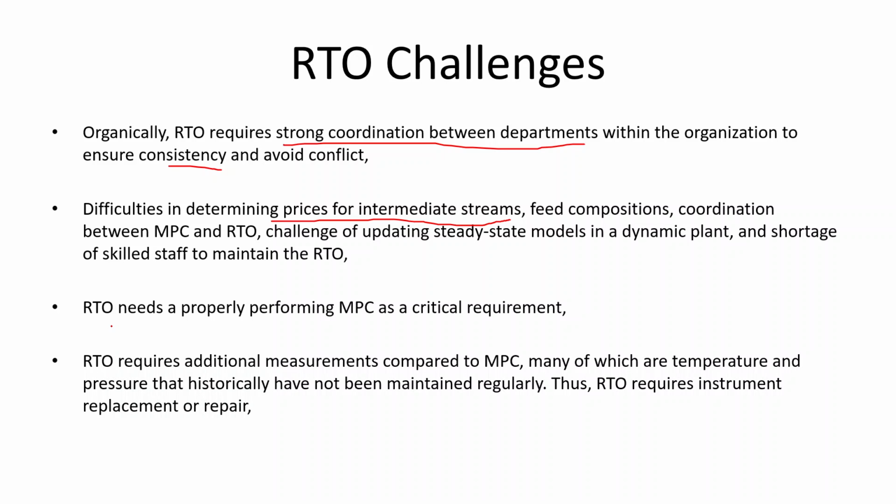It has to be put in the process control layer, or in this case the MPC, so that the MPC can then tell the set points to the process control system, the BPCS. The BPCS is very detailed. This one is slightly less detailed. This one is also not so detailed, slightly less than the MPC, and then up to scheduling and then planning.